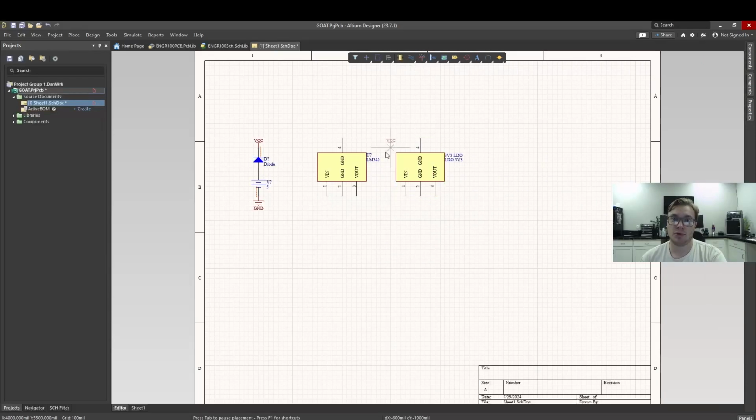And then we can place our VCC nets on these VIN pins. So this means that pin 1 and pin 1 on both of these LDOs get connected to this leg of this diode. That'll become important when we actually go to design the board. So then these pins need to be grounded.